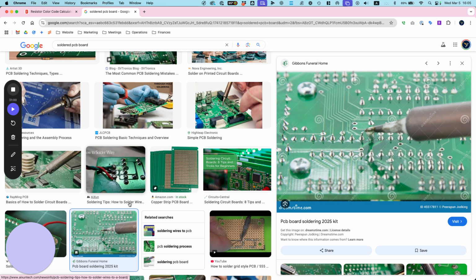Okay, so you could do the rest here. You could just bend this over. Let me check the rest of your resistors look good. So you can trim one. You could trim that. You could bend it over, solder, clip the end. Okay? Thank you. You're welcome. Now that's if you have this. If you're lucky enough, you don't have to do that because you already have the bridges.